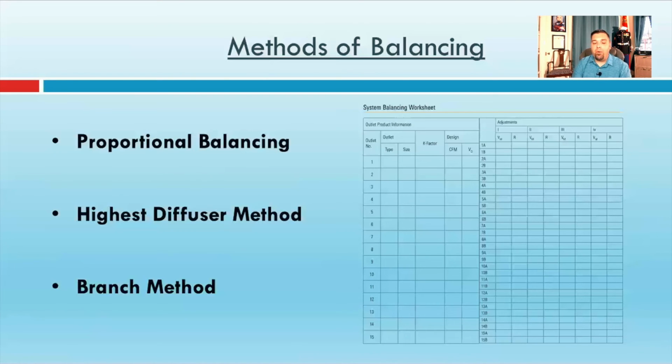So really important to avoid big pressure differences in spaces when you close those doors, right? So that's why most people put returns in every bedroom. So that way you don't depressurize hallways or cause combustion appliance zone area issues based on pressure. A lot of that boils down to testing and balancing. So I highly recommend you guys get on board. A lot of tools that are needed, you most likely have in your shop already. Maybe an airflow hood's probably the only thing you have to purchase.